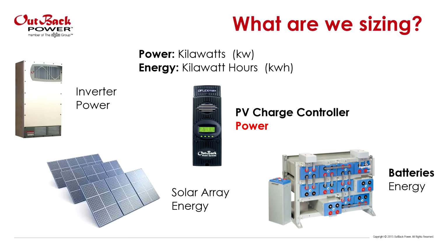Most charge controllers have a power limitation, so be aware of the maximum power your PV array can produce and ensure your charge controller is rated appropriately. We'll be sizing this based on power, but this does directly affect the amount of energy you can pass from the PV array to the batteries over time. Okay, so we're going to be sizing all of these components, but remember, we're just doing a simple ballpark estimate type of calculation.